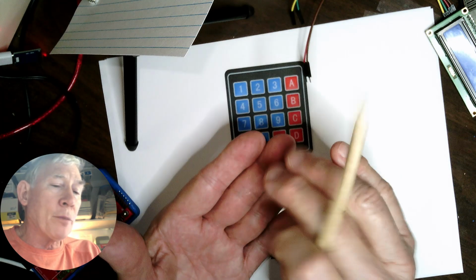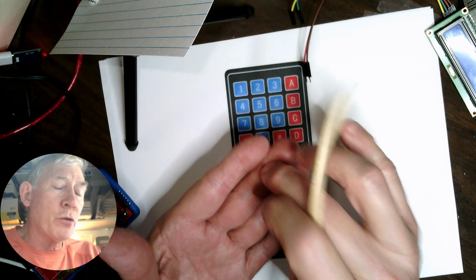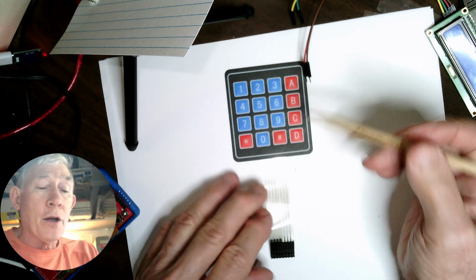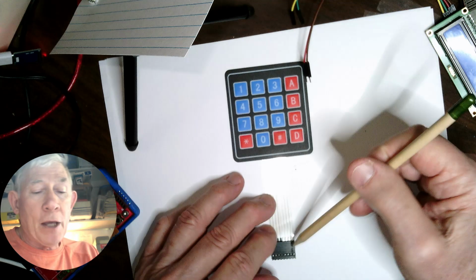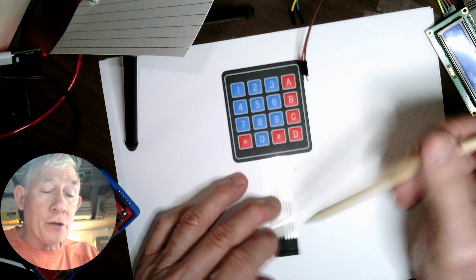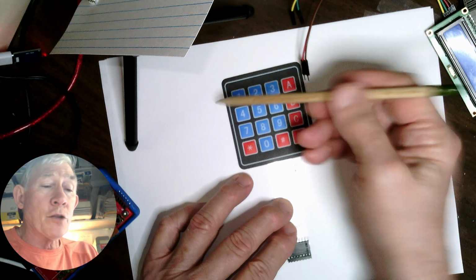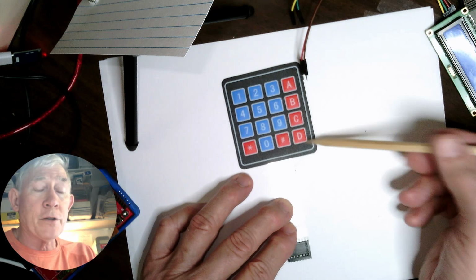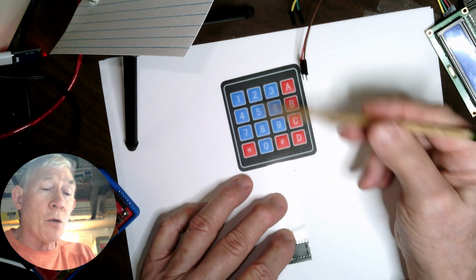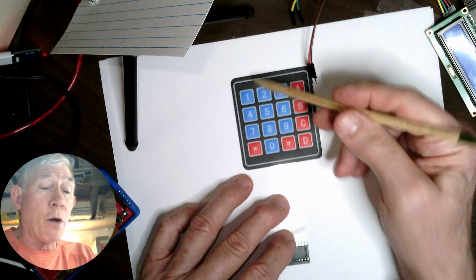And so every one of these buttons has 2 pieces of membrane. One's kind of bubbled up a little bit, and when you push on it, you short the top to the bottom. And the top maybe has the columns, and the bottom maybe has the rows. So we have row 0, 1, 2, and 3, and these wires run all the way to all 4 buttons. And then we have columns 0, 1, 2, 3, and the wires run to all 4 buttons.